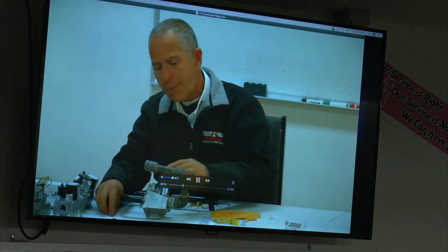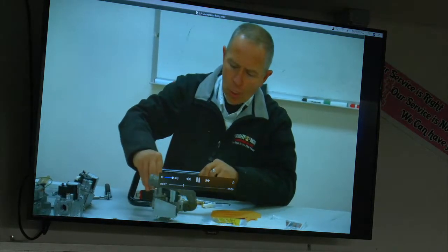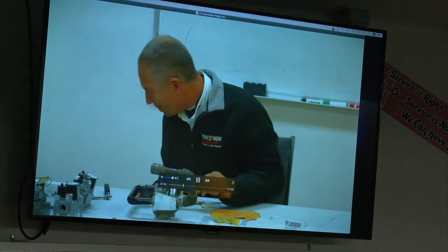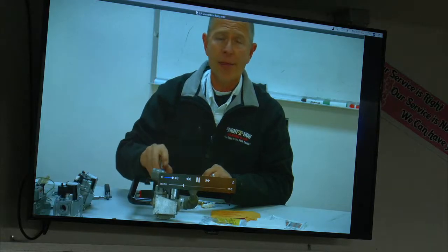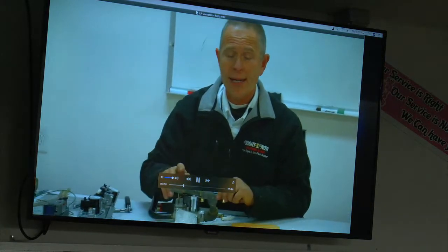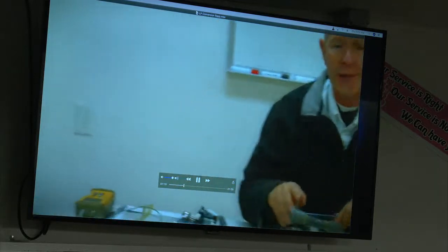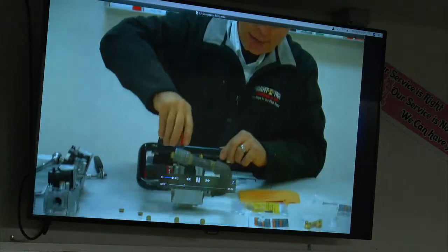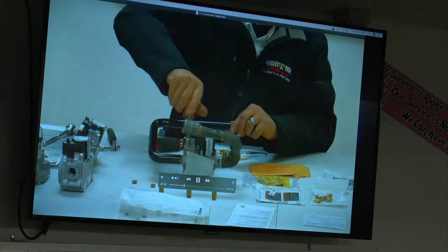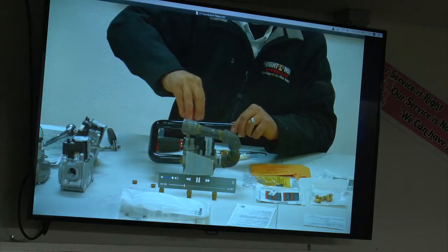And when we put the spring back in, and then we put the set screw in, we tighten the set screw down all the way till it bottoms out at the bottom, and then we're going to turn back 1 to 1.5 turns, so that we start out in a pretty neutral position with the spring not fully compressed inside of the valve. So again, we're going to tighten that rascal all the way down, and then when you feel it just barely stop, turn it back 1 to 1.5 turns.